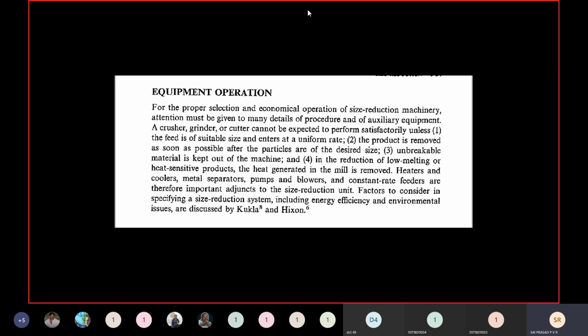The pile up of the product enters the zone of crushing, and unnecessarily it will be blocking the materials to come inside the system. As the height of the pile increases, what will happen? It completely fills the machine, and only the crushed product will be subjected to crushing. So energy is given to the machine, but crushing is not taking place. So hence, the concept is what? As we are sending the feed from the top at a constant rate, at the same time you try to remove the product as it is falling down by some mechanism. Usually conveyor belts are used.